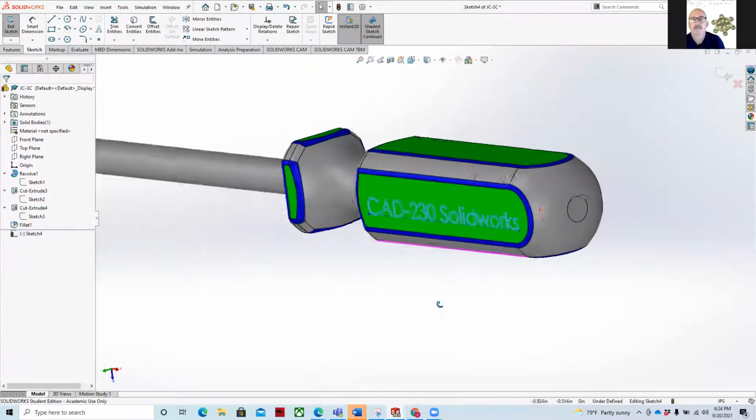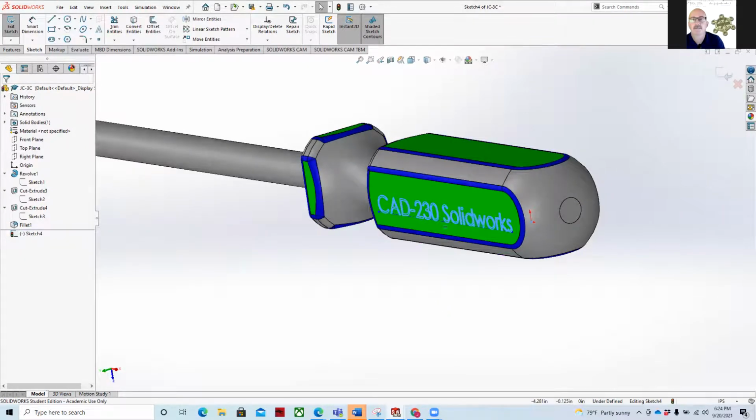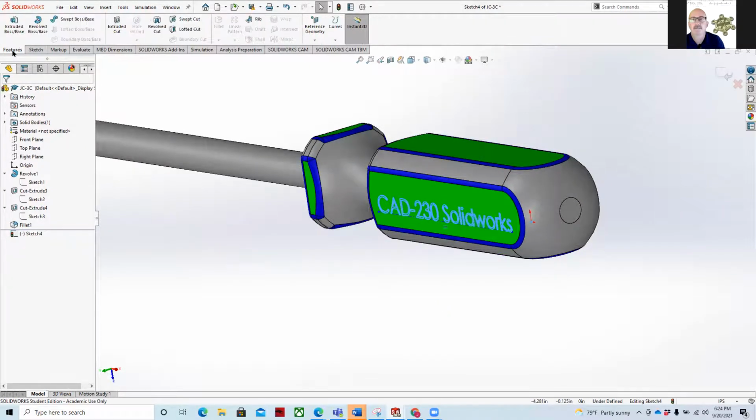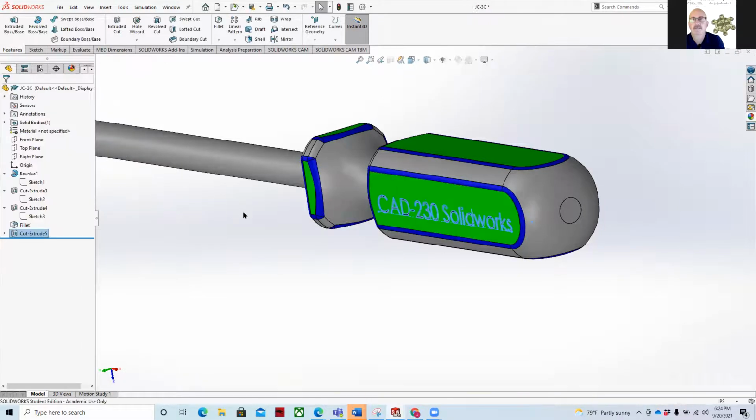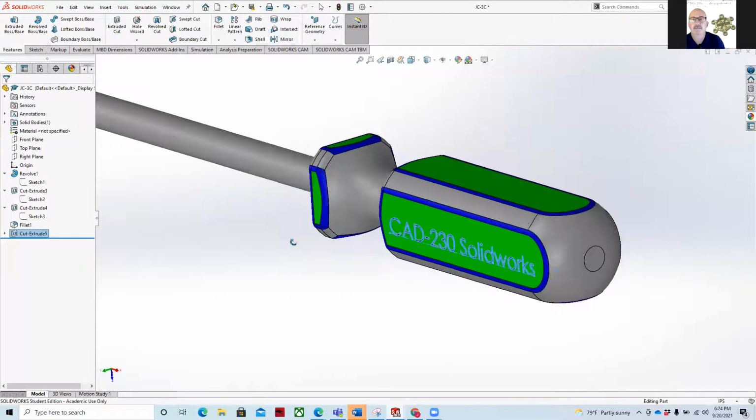And then if you want to, you can extrude cut it. I can go to features. So I'll engrave my name on it, and I'll say extrude cut, and I can bring that in 0.05. That's a little much. Let's go with 0.02. Perfect. A 3D printer will put down a layer about 0.1 to 0.01 to 0.03, depending on how we have it set up in the tolerances.